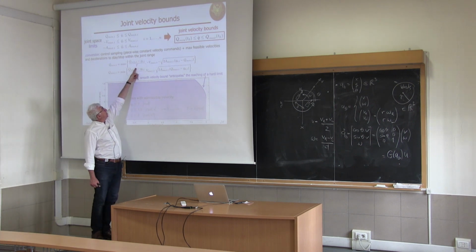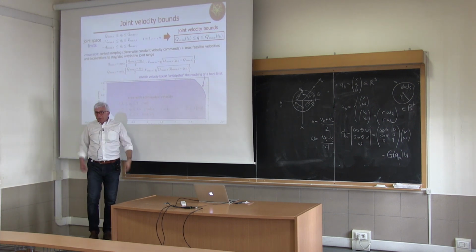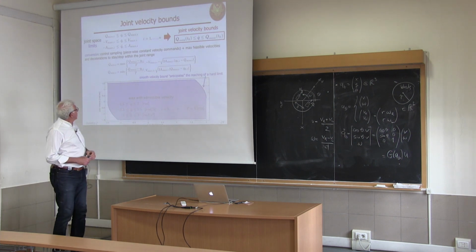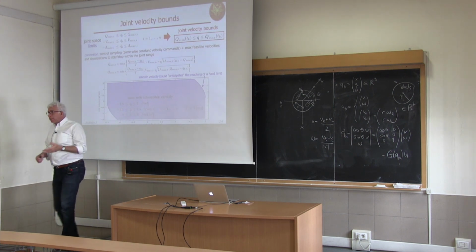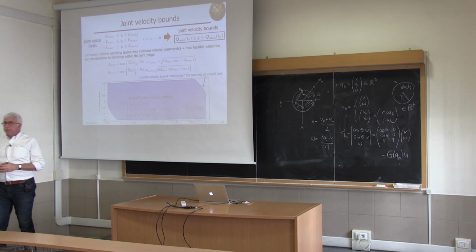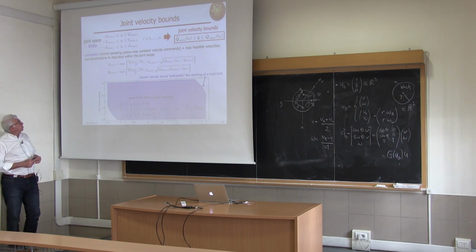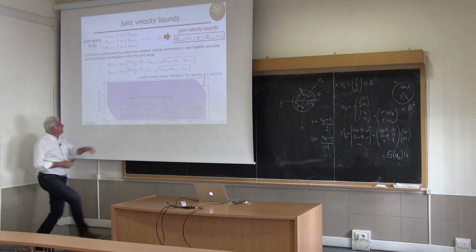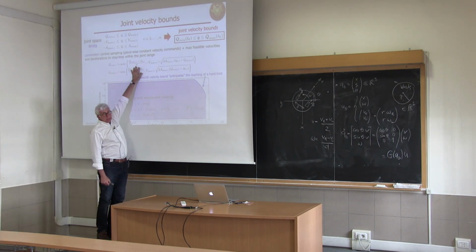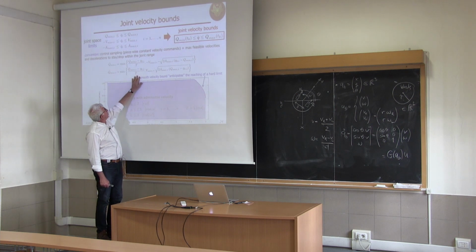And this is the bound coming from the joint range, which simply says that if T is the sampling time, and we will keep this command for an interval of sampling T, then with this speed, we may reach or not the lower bound for the joint I. So we give a limit. This is the maximum velocity in this configuration that will keep you inside the joint range. And same for the upper bound, and we take the minimum of these values.